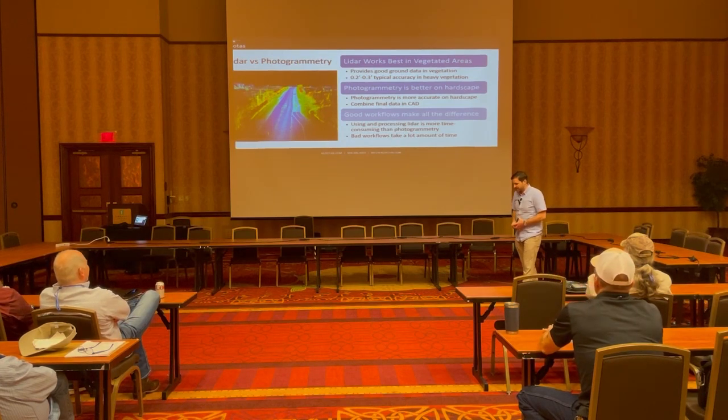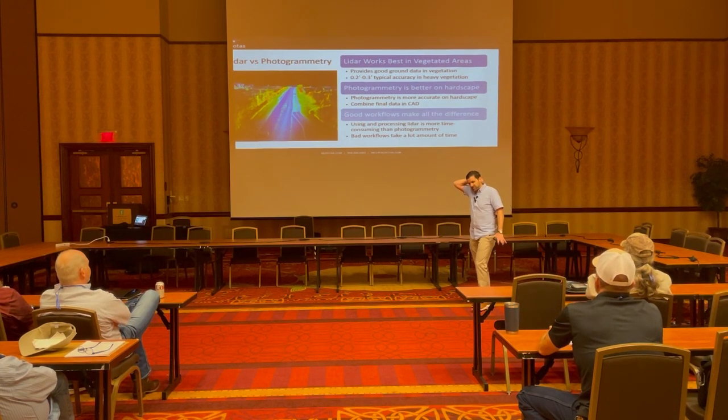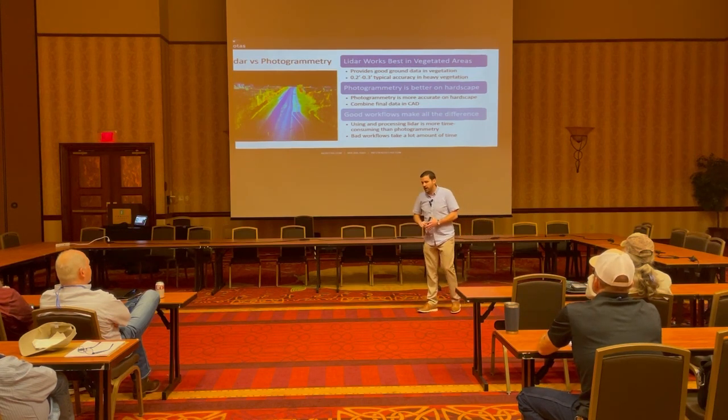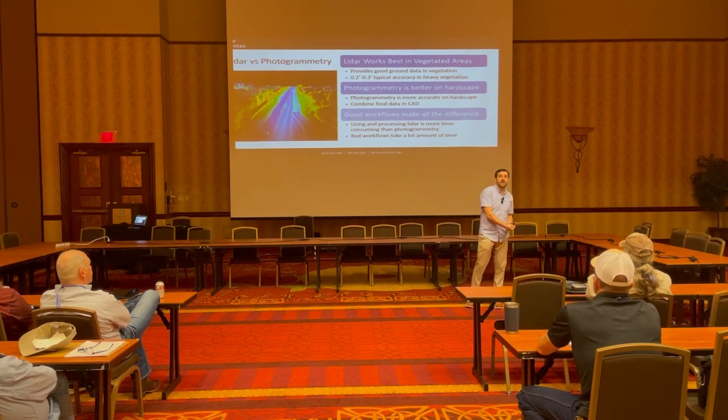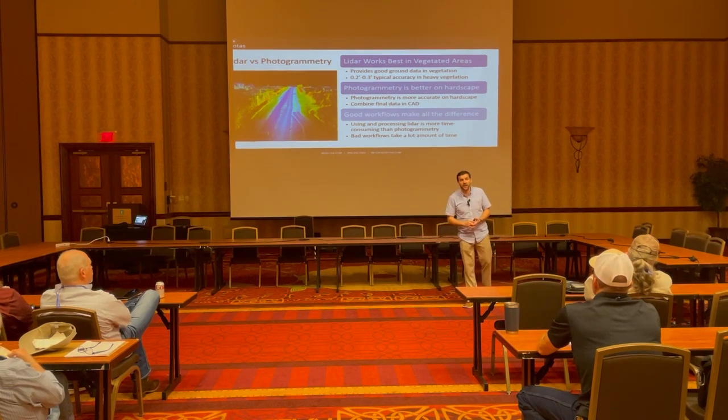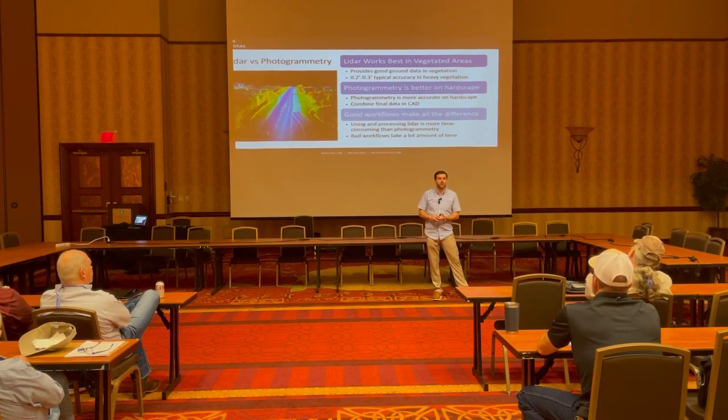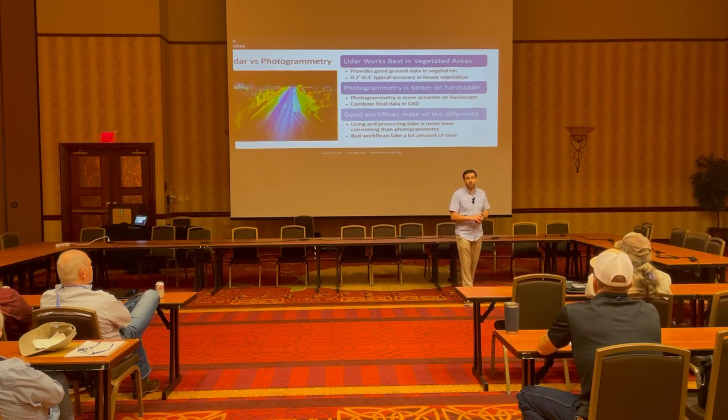One of my favorite things is that a lot of LiDAR drones nowadays, in fact, any of the ones that I would recommend, carry both LiDAR sensors and photogrammetry-capable cameras in the same integrated payload and fly them in the same flight. And that means you can take that drone, you can fly it, and if you don't need LiDAR, we just don't touch the data. Not because it's not useful data, but because it's more expensive to process, at least than photogrammetric data. So oftentimes people will fly a DJI L1 or a similar LiDAR drone and process it in photogrammetry only, and that's perfectly acceptable and oftentimes a good workflow.